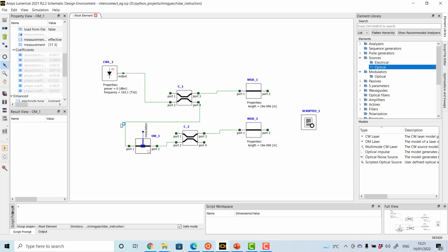The second beam goes through an optical modulator, and it's important that the beams all come out from a single input because you want to keep some kind of phase relationship, and that's how it is typically done in an experiment. An electrical voltage can be applied to this optical modulator. There is this pin which you can see here, the modulation pin, and in the later example we will see how this can be connected to an actual voltage. At the output port, you end up with a modulated signal, and similar to this C1 here, you can have C2 and so on. Typically, if you had more elements below, you could draw a signal out from here and modulate it more, and so on.